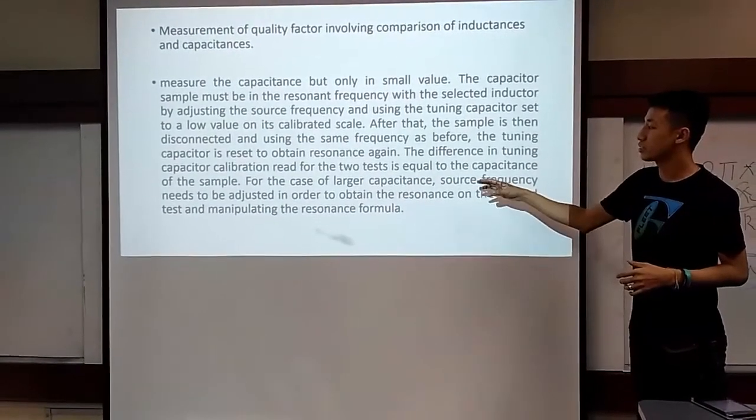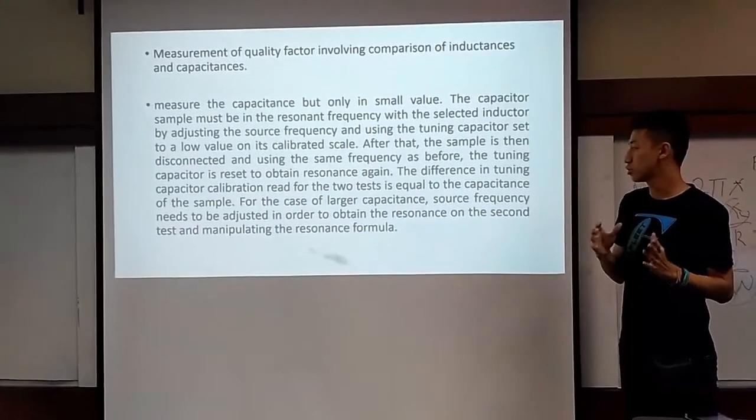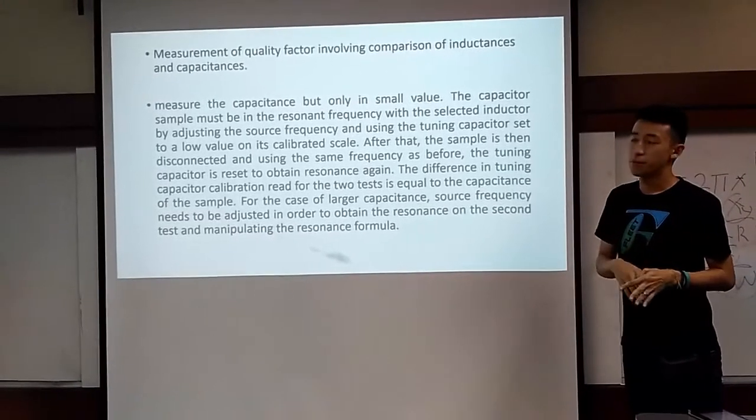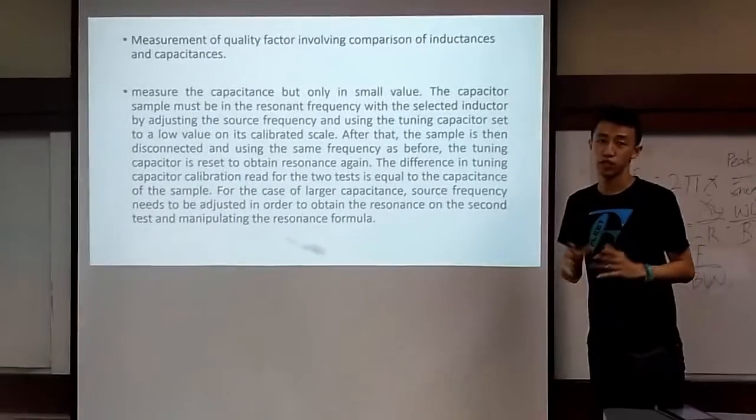For the case of a larger capacitor, the source frequency needs to be adjusted in order to obtain resonance on the second test, manipulating the resonance formula. That's all for the applications of the Q meter.